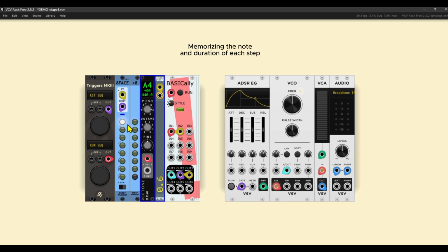This red flash indicates that the module is ready to memorize, in the current slot, the current settings of all associated modules. In our case, reftone is the pitch to be memorized, and voltage its duration. By switching the switch back to the R position, the recording of the associated module values in the slot is confirmed. The red flashing then stops and the LEDs turn light green.